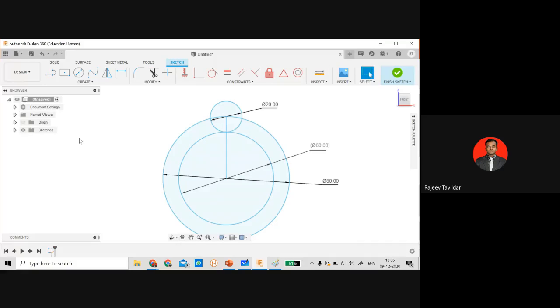To draw the initial position of the roller, I have drawn an additional circle. This is going to be called the prime circle now. The second circle is going to be called the prime circle, and the inner circle is going to be called the base circle. Okay, I'll delete all the dimensions here.